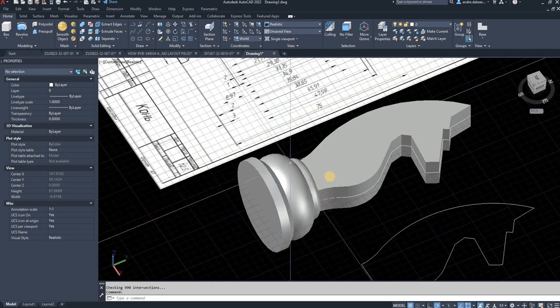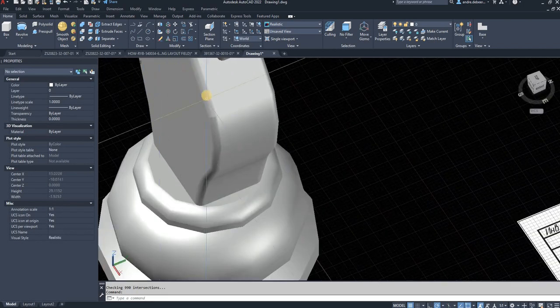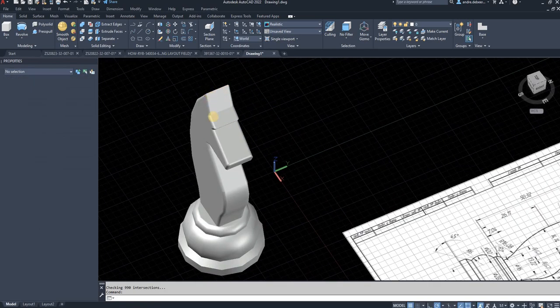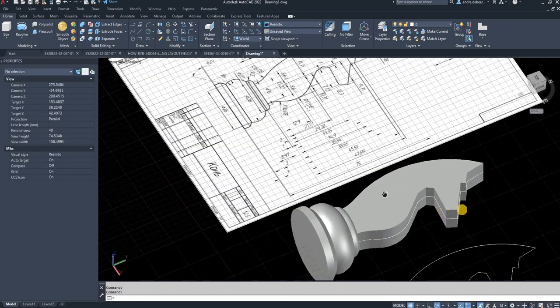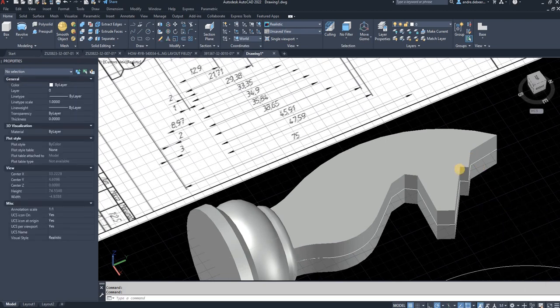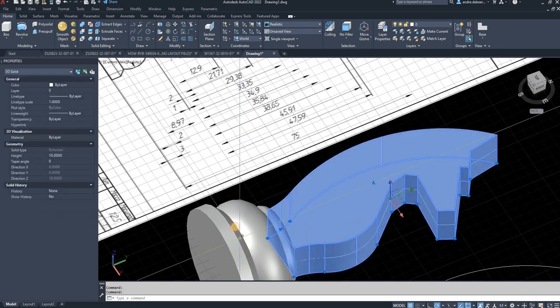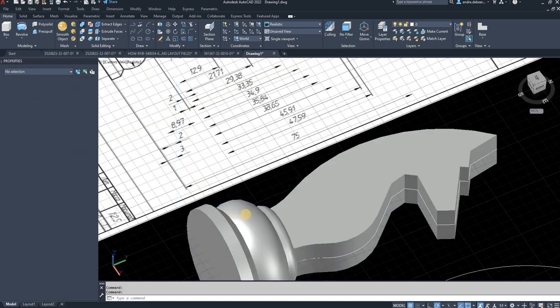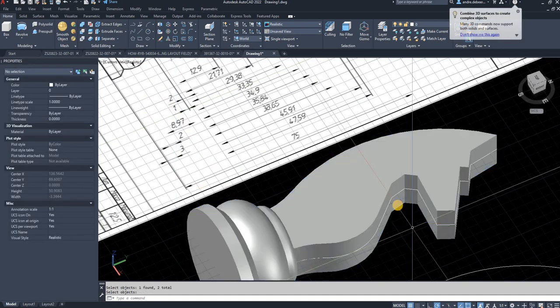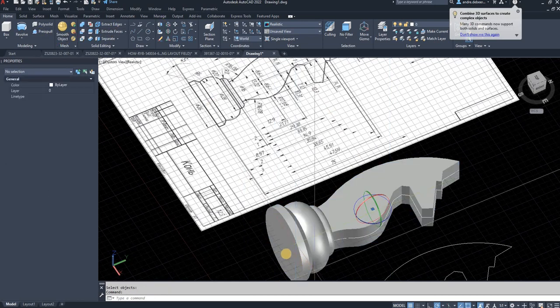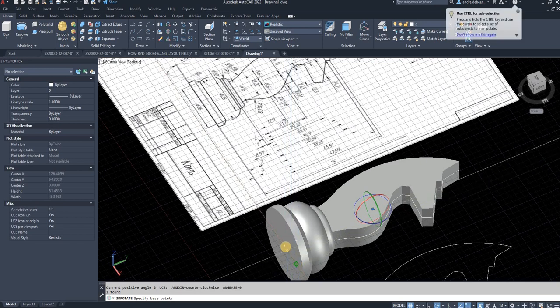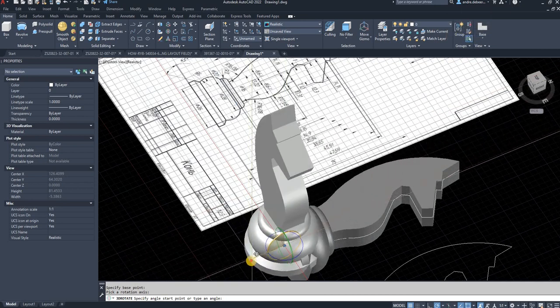So you can stop here if you want, but as you can see in my example, I used the chamfer function all around just to give it a nicer look, a more smooth look instead of this sharp look that you get from just a normal press pull function. So the next thing you can do is you can use the solid union function. Select the two pieces, then you can rotate with the 3D rotate function. Use this bottom as a center point and rotate it 90 degrees.